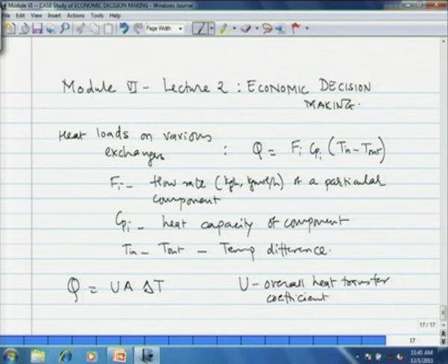We can have a range of overall heat transfer coefficients available. Well, you can get these from any standard text like Perry's Chemical Engineering Handbook or the book of D. Q. Kern, Process Heat Transfer, the range of overall heat transfer coefficients for a particular combination of streams.